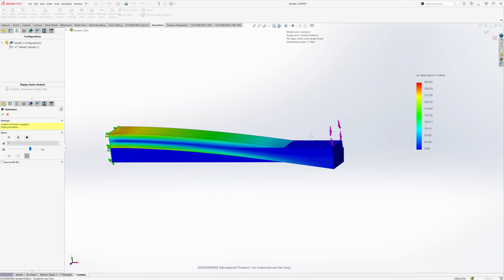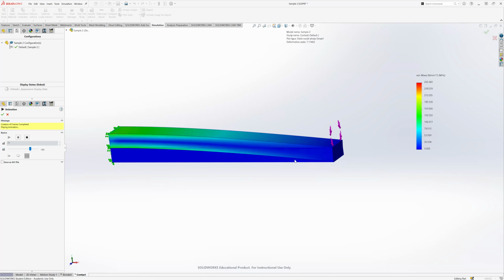So again, this is not realistic at all, unless you're just doing this for an example like this. This is where you really want to be careful. Animate is really, really useful. In this case, you didn't really even need to animate it. You can clearly see that one is going nowhere. But if you apply maybe a global condition of, let's say, free, and you're getting a result that looks something like this, then this tells you that your free global result is probably not working too well.